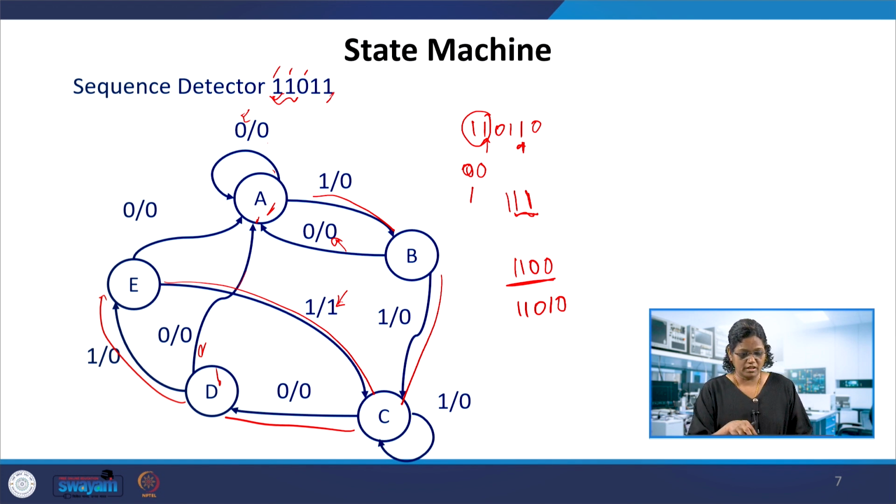That is easier than instantiating the D flip-flops and all the combinational circuits for the next state logic and the output logic. But in the synthesis process, we will see the difference between the instantiated one and the code we developed using the state machine model.